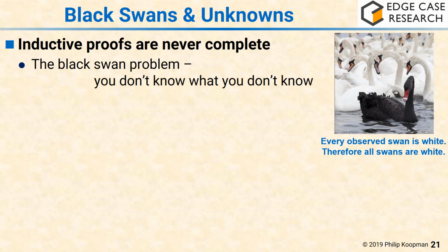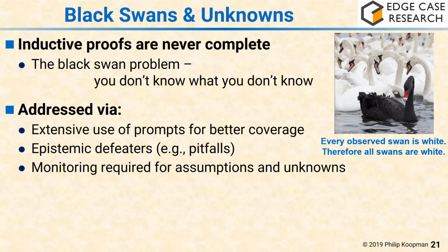And so in your safety case, it's okay to say, we think we have everything covered, but there's always the chance that we miss something, because that's the real world. That's always been true of hazard analysis. It's just going to be more upfront and center in self-driving cars. And so what you do is you say, fine, our plan for what if we miss something is we're going to do monitoring.